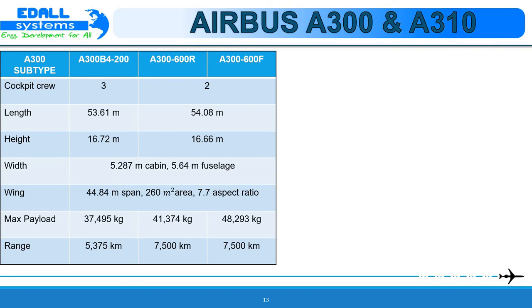The succeeding three-digit number represents the aircraft series, the engine manufacturer and the engine version number respectively. For example, in this A300-600R, the code is 6 for series 600 and 0 for engine manufacturer and the engine version 0. Thus, the aircraft number is A300-600.